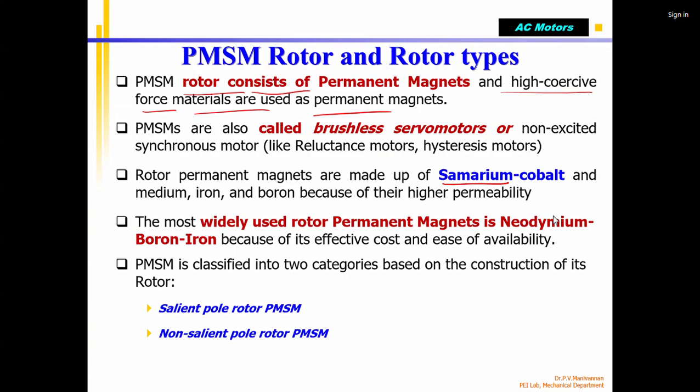That is a different topic, not our subject. Generally, a permanent magnet can be made of regular ferrous material, iron plus nickel plus cobalt. In that case the motor size will be bigger, the rotor size will be 3 times bigger or more, with more weight. But in an electric vehicle, you want a smaller motor with smaller weight and more torque. That means your vehicle will go a longer distance without wasting energy, correct?